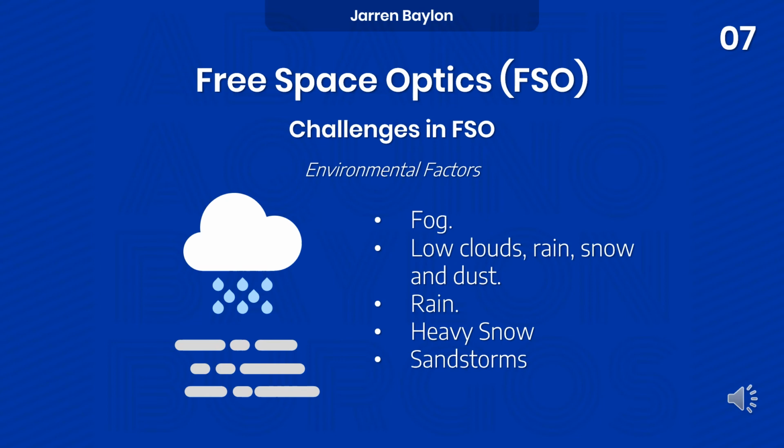So there are various challenges in free space optics. Here, we will discuss the environmental factors. So first is the fog. The fog is composed of water droplets between a few and 100 microns in diameter. This allows absorption, scattering, and reflection to occur when laser beams pass through it. Now, fog is a major challenge to FSO communications and can result in atmospheric attenuation of signal. Especially with heavy fog, this can result in a complete outage of the service.